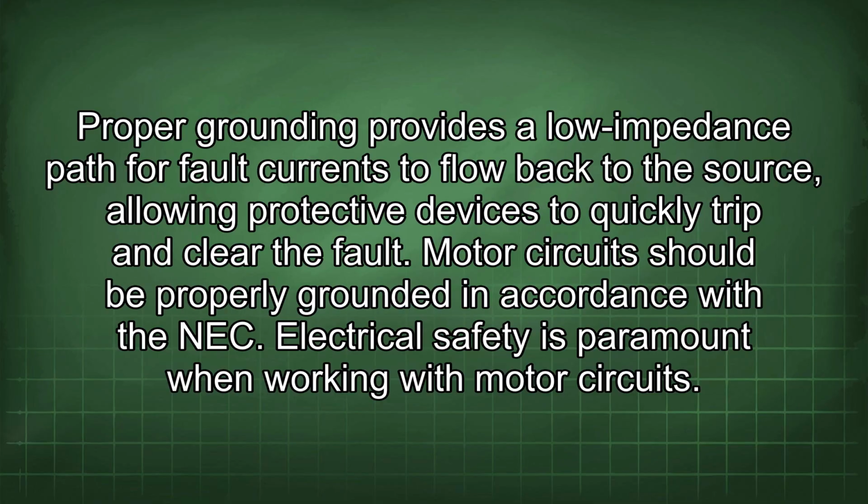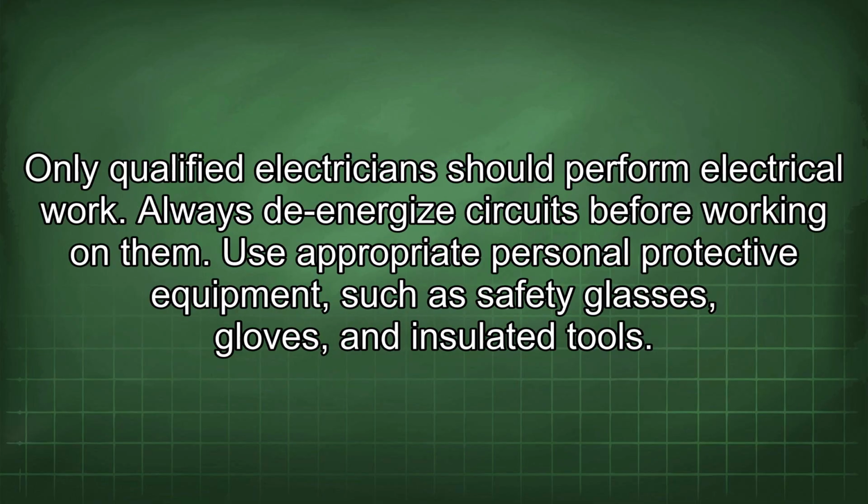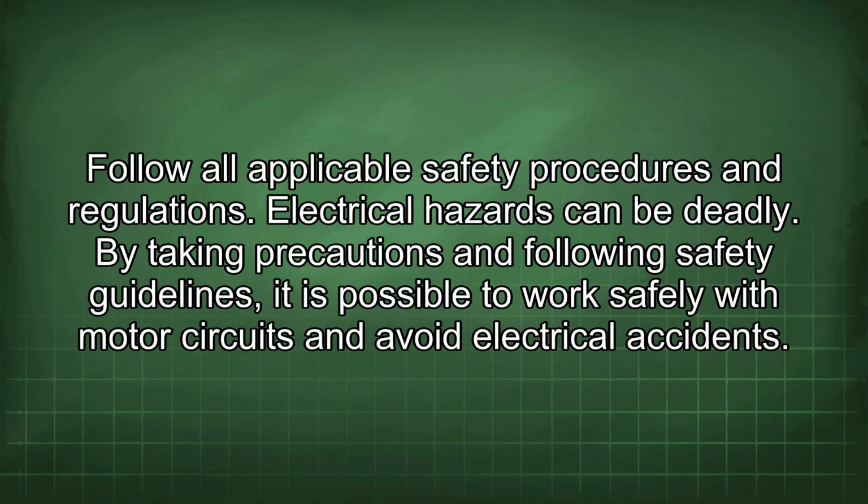Electrical safety is paramount when working with motor circuits. Only qualified electricians should perform electrical work. Always de-energize circuits before working on them. Use appropriate personal protective equipment, such as safety glasses, gloves, and insulated tools. Follow all applicable safety procedures and regulations. Electrical hazards can be deadly. By taking precautions and following safety guidelines, it is possible to work safely with motor circuits and avoid electrical accidents.